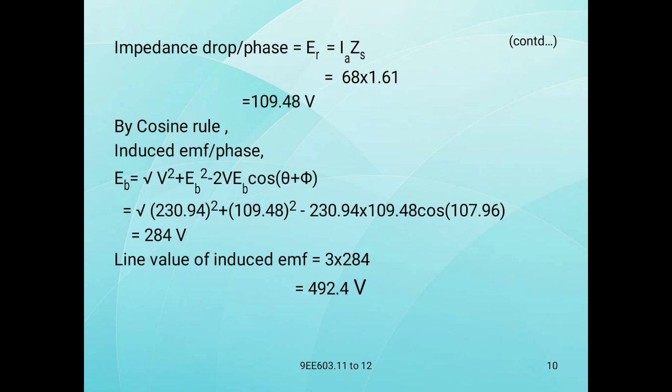The line value of induced EMF is root 3 into 284, which gives 492.4. That is the voltage for line induced EMF.